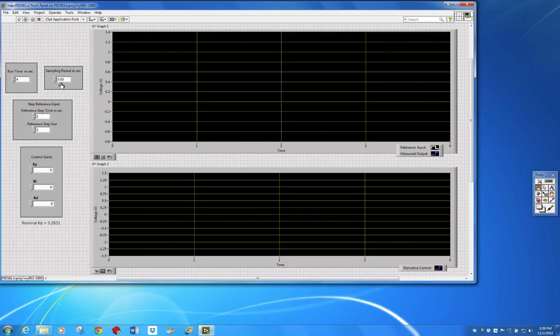You might recall that for this particular analog plant, with its vibration mode frequency at roughly 1 Hertz, I indicated earlier that the absolute minimum sampling rate to control that vibration mode was going to be 2 samples a second, and 2 samples a second corresponds to a sampling period of 1/2 of a second, or 0.5 seconds. And so the 0.05 sampling period we've chosen here corresponds to sampling at 10 times the absolute minimum sampling rate to control this analog plant's vibration mode.